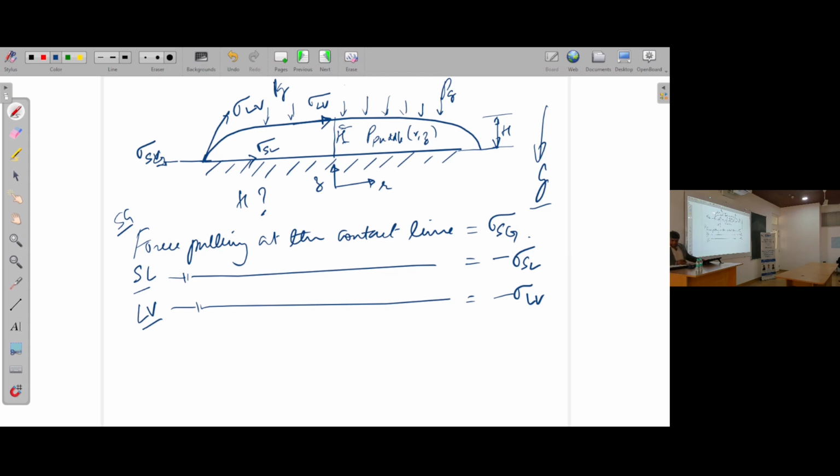Now, if we actually do a pressure balance, if we want to understand what is the pressure and what is the effect of this, all of these forces must be balanced in accordance to PG and in accordance to what P puddle is doing here. So the first thing we'll try to find out is what is P puddle.